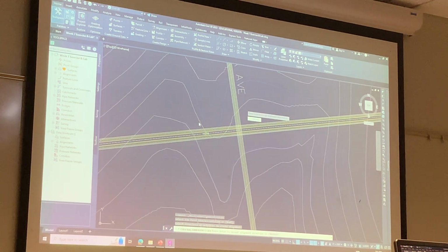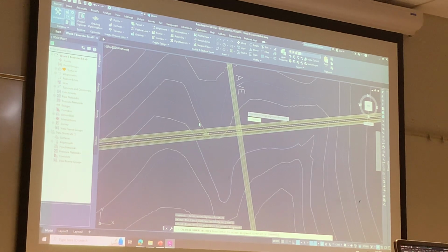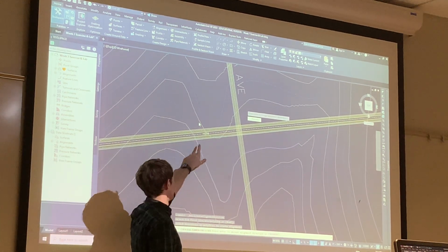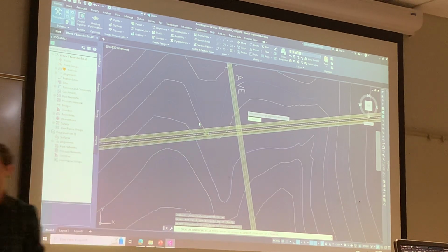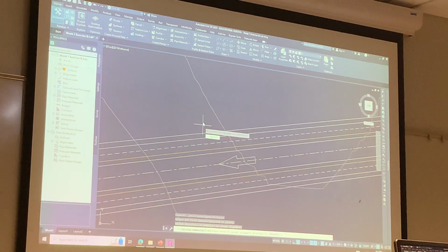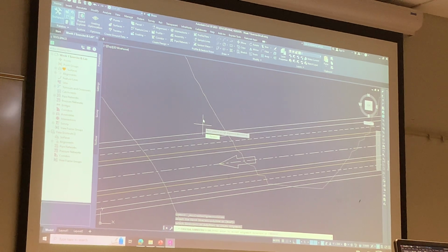And remember though, it's gonna ask you which direction do you want to go? It puts this little arrow right there. I'll zoom into it. Mine is pointing to the left. I don't want it to point to the left. I want it to point to the right. Did you do profile? No, he did alignment. Alignment.